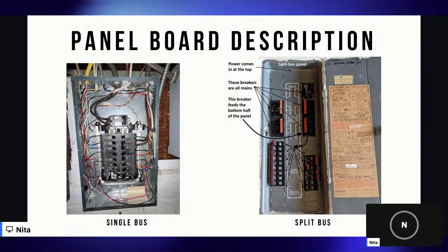You can have your enclosures, your panel boards, in basements and garages, as long as you meet the clearance, which we'll talk about in a second. They may not be in bathrooms, closets, or behind appliances. You can't put a picture over it, not behind any decor. Sometimes I've seen it in the bathroom.